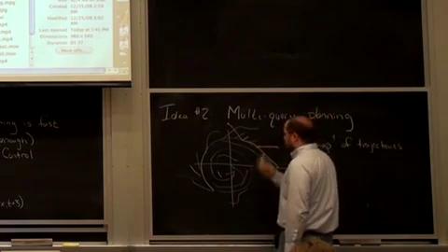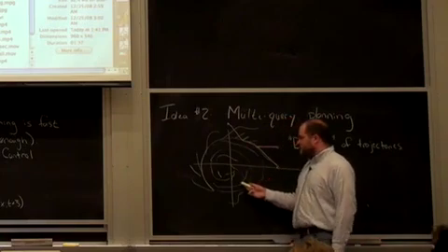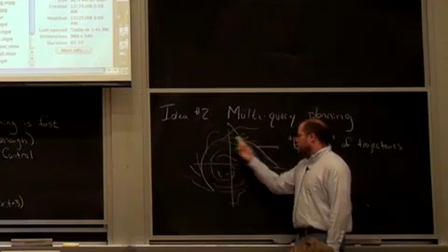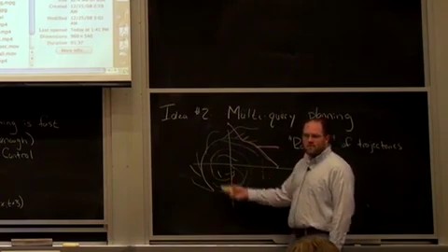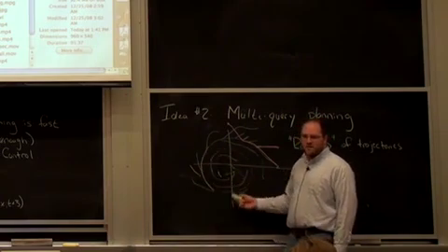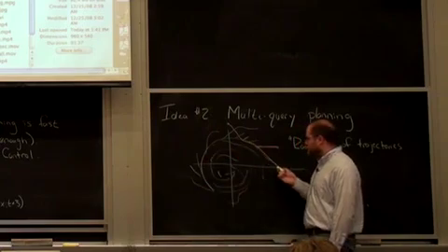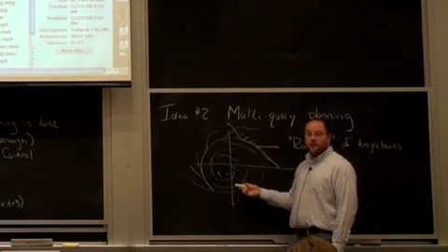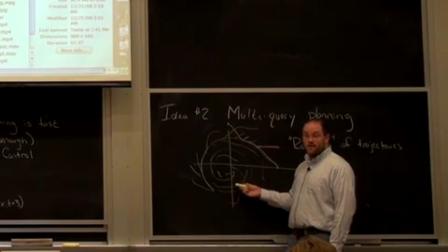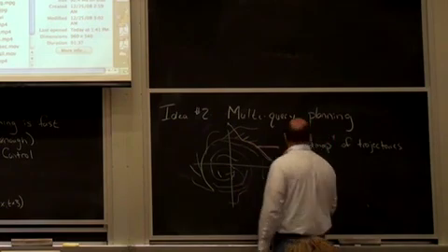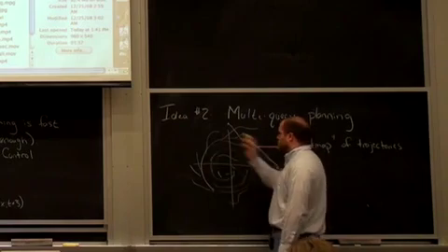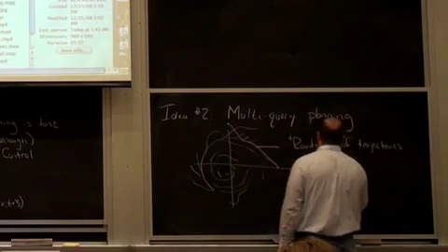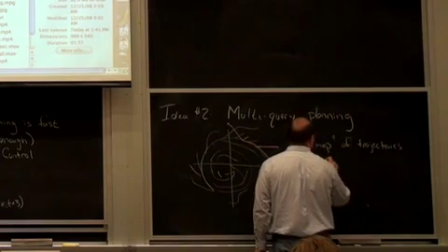If all you care about is getting to the goal, then all you need to do is connect to your existing roadmap and ride it to the goal. If your roadmap is so rich that once I connect to the roadmap, there's actually a bunch of different options, a bunch of different paths I could take through the graph to get there, well then at least you've got a discrete planning problem and you can do A star on it or something like this, right? And effectively the trajectories I've already generated will turn this back into a discrete planning problem.